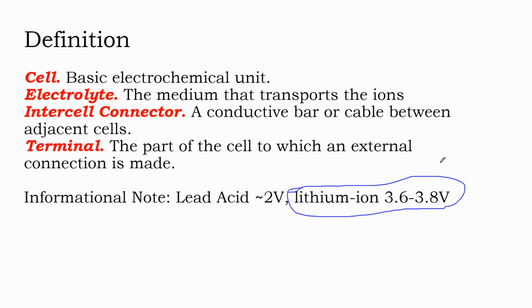So with a sealed battery where you can't apply a very rapid charge, it's weird because physically lithium ion is able to take a higher charge and a more rapid charge, and we see that reflected in its natively higher voltage rating than lead acid.